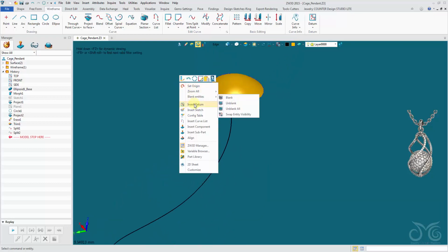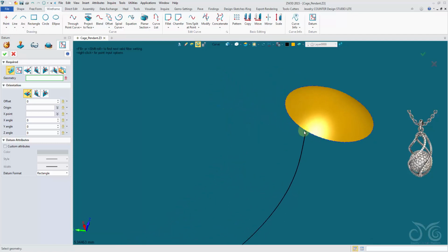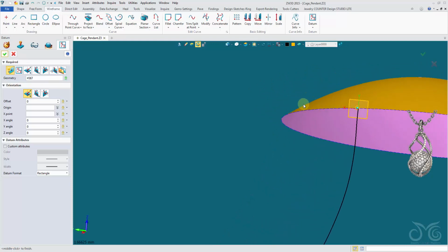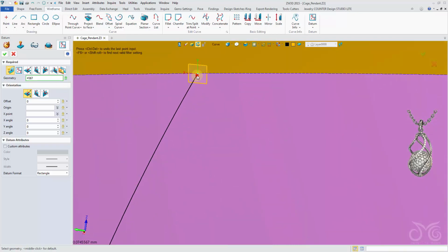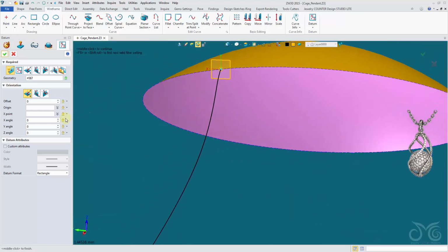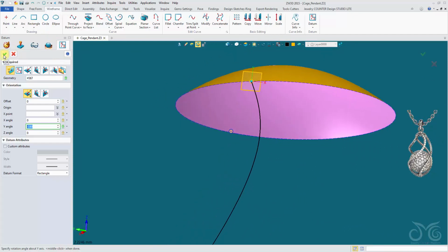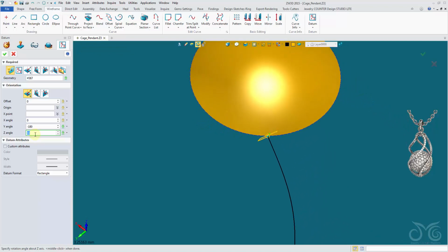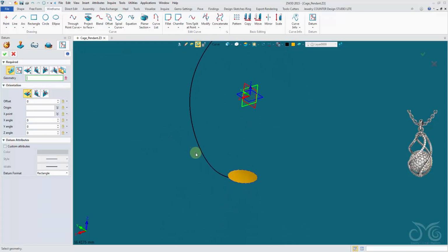Okay. Now we're going to sweep a rectangle along our curve. We start off by inserting a datum. Let's snap to end point of the curve. Change our entity filter to critical to make sure. Okay, the orientation of our datum plane. Okay, it doesn't seem to be at the end point there. Let's pick that again. Let's snap in there. The orientation, let's flip around our Y angle 180. Confirm the operation. In fact, I might rotate my Z angle a little bit to level it out.